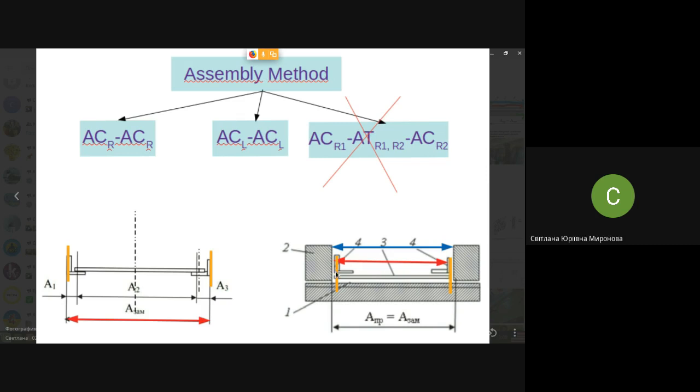And how to find the position of this real base 1 with respect to the real base 2, which we are really interested in? We make an element of tooling, here in the middle, which carries both of these bases, unites them into one structure somehow. And temporarily, in a process of locating, we use this assembly tooling, which is the carrier of all the bases we need.